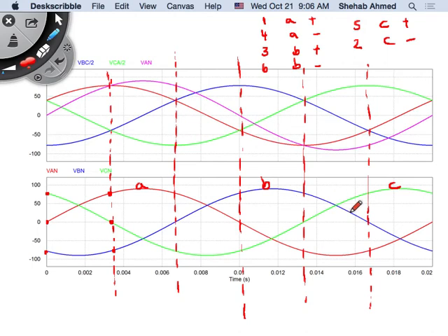Yeah, you look at phase C, positive, so it's 5, right? And then phase A, positive, would be 1, right? And then what else? And phase B, negative current will be conducting. And phase B is 6, right? Remember we said that if they're all diodes, then we have a balanced system. It's like wires going through there.